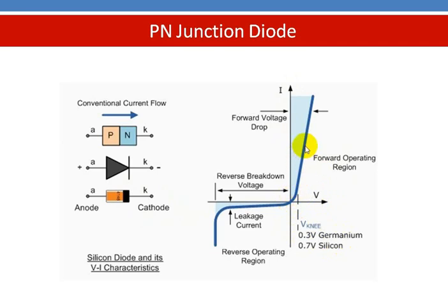As the current through the diode increases, you can see that the voltage across the device also slightly increases. You can see here this line slightly moving away from this vertical axis. From this point to this point indicates the voltage drop across the diode. Here it is minimum, whereas here it is large. Therefore, with increase in current, the voltage drop is increasing.